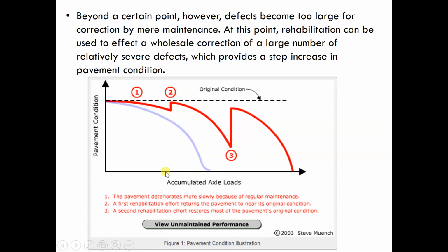This will be determined by the time as well. You design for a certain axle loading, for example 1 times 10 to the power of 7, which we call the equivalent standard axle, which we're going to cover in Highway 2. But it's time dependent. At an earlier time you have less accumulated axle loads, and further down the track you have more axle loads. So with time, the amount of axle loads increases.